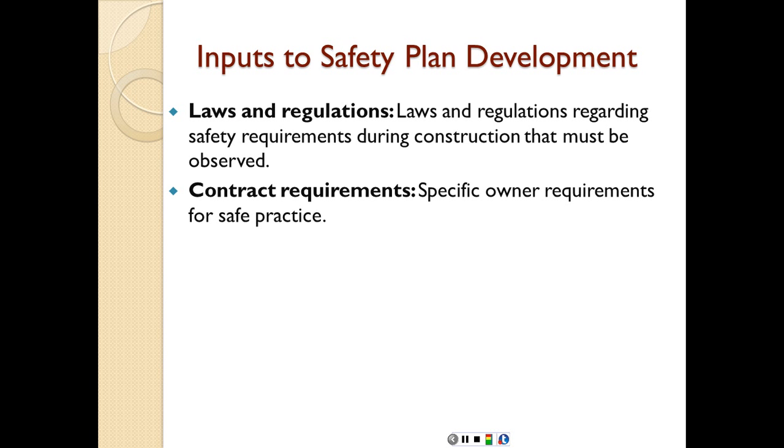As we said before, these may be over and above or more stringent than the requirements of OSHA. If OSHA, for example, says you have to have fall protection at a certain height, some owners may say, okay, we're going to lower that height to have an even more safe work environment.